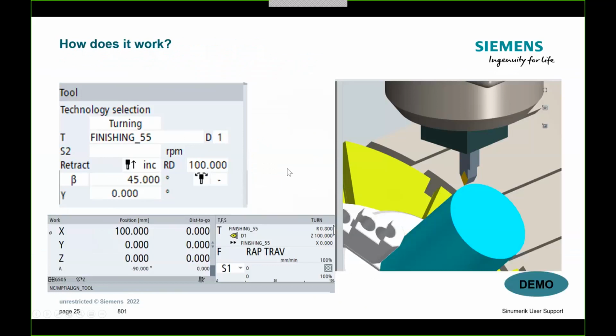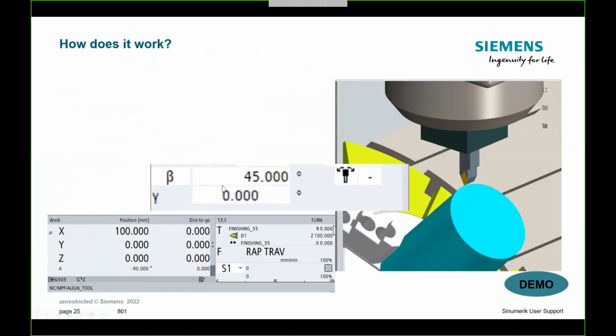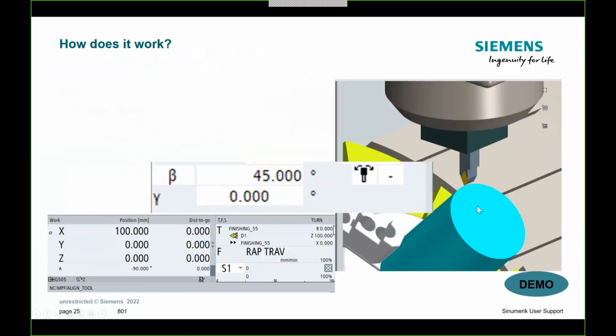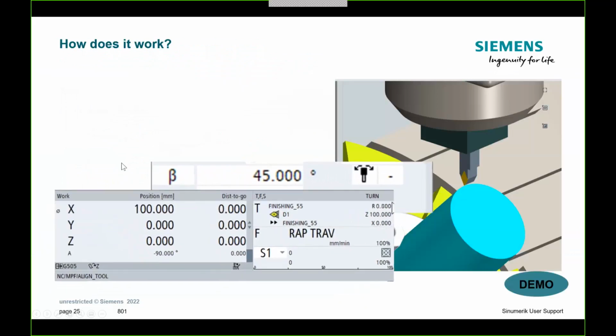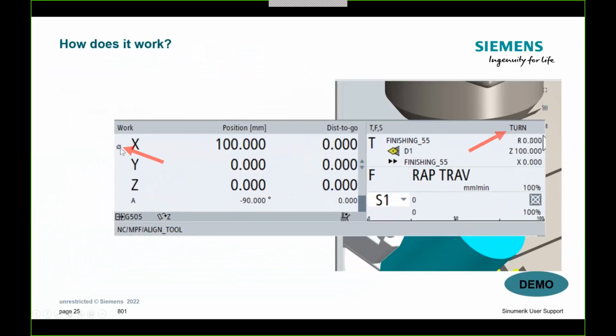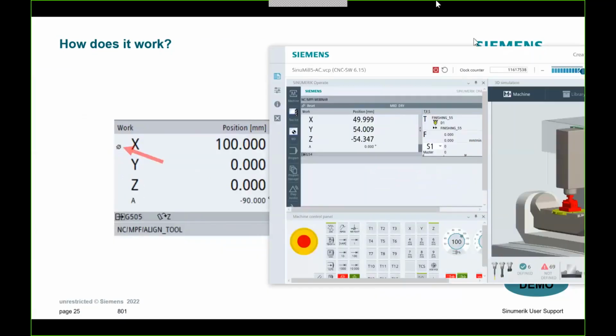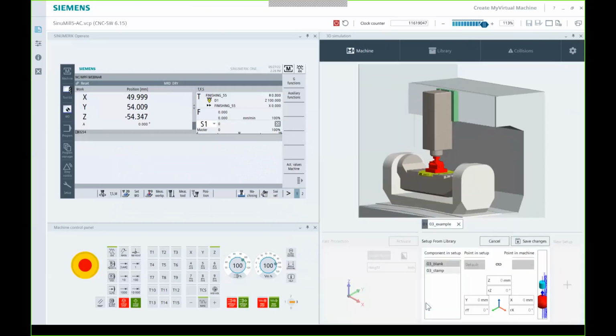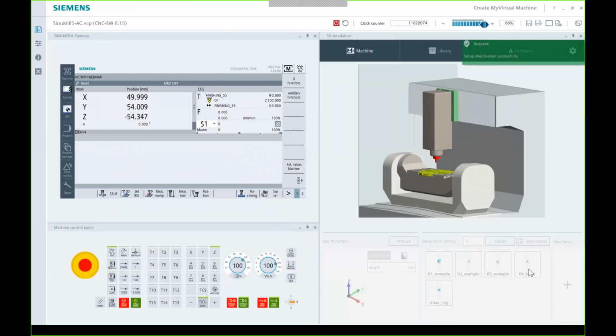So how does this all work? Rotate this B, the system will rotate. And then if you watch, as soon as that turn tool carrier turns on, I then get a diameter here telling me that my x-axis is positioned in diameter. When that tool carrier is off, my diameter goes away. So let's take a look. Machine, and let me get myself back here to the correct.